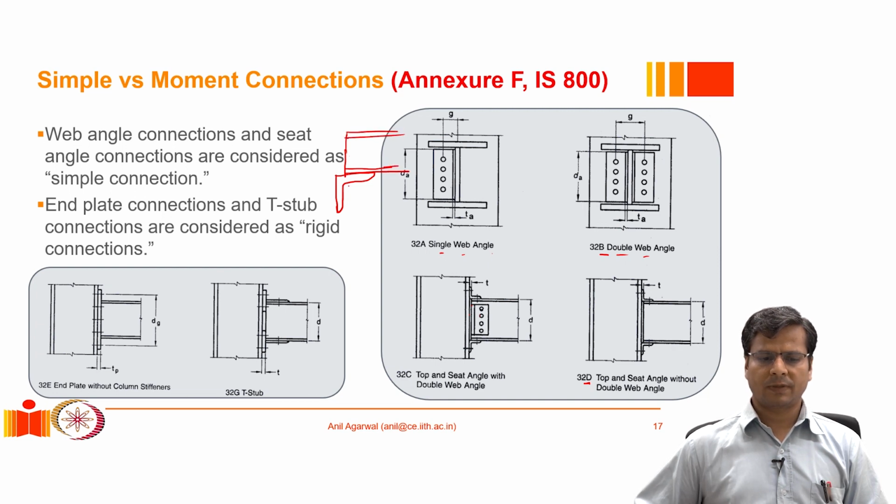And because of that, this portion of the angle has to resist this load, and that will produce a very large bending moment demand or a shear force demand at this cross section of the angle that I have just drawn, right? So in order for it to be able to resist that load better, sometimes we may put a stiffener here. That stiffener will basically strengthen the angle.